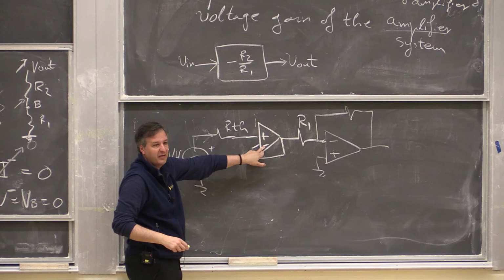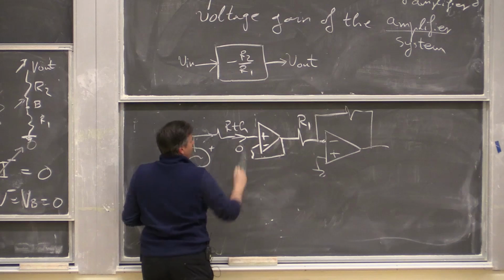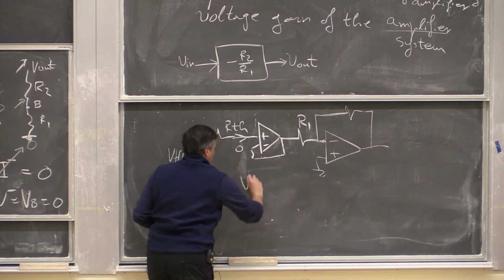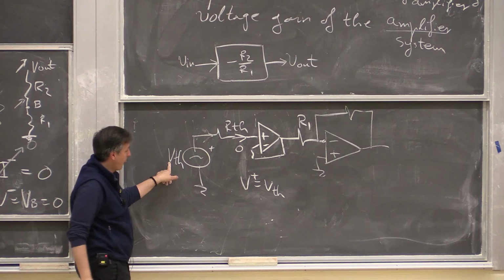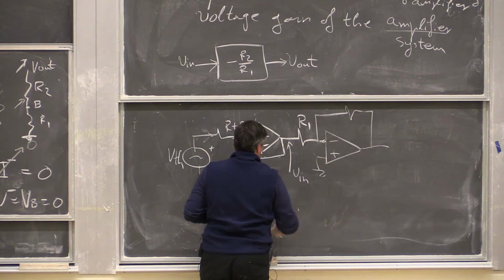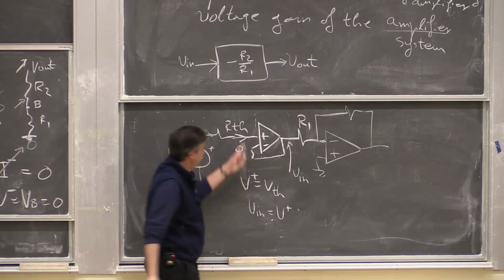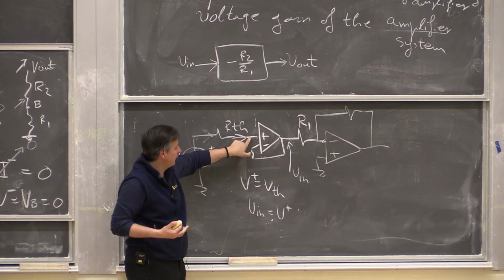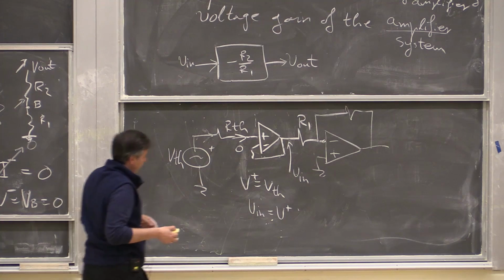Okay, so this is a buffer. We feed back to the negative port. Feed here the positive port. There is 0 current flowing here because that's I plus. Okay. So V plus here equals V Thevenin. And then V in equals V plus. Because this is a buffer, right? We did that. The transfer function for this buffer is basically whatever is at the plus terminal, that voltage it passes through, right? We did it last lecture.